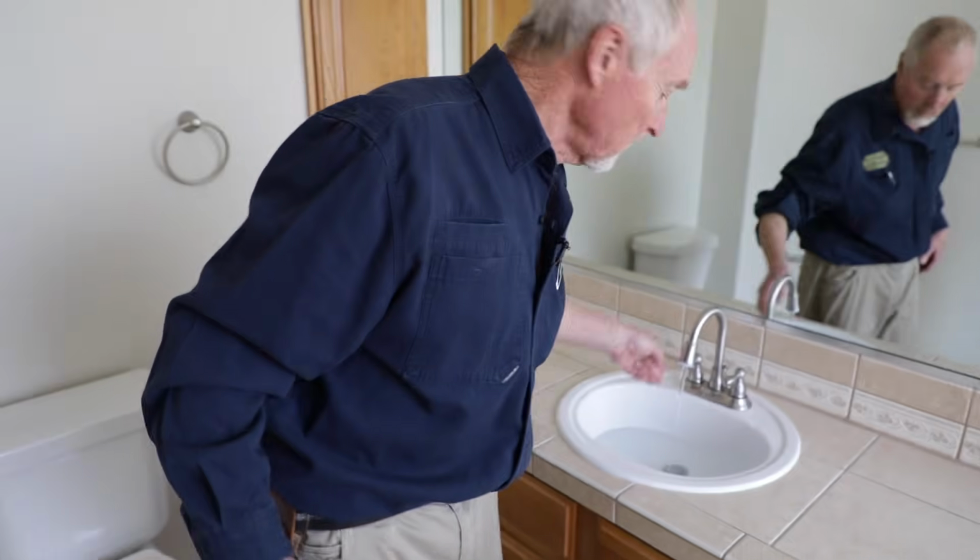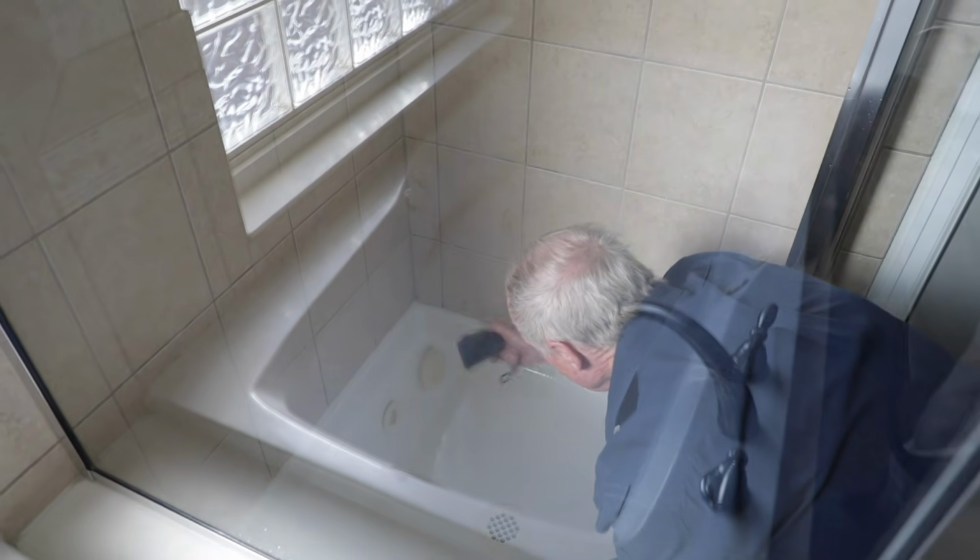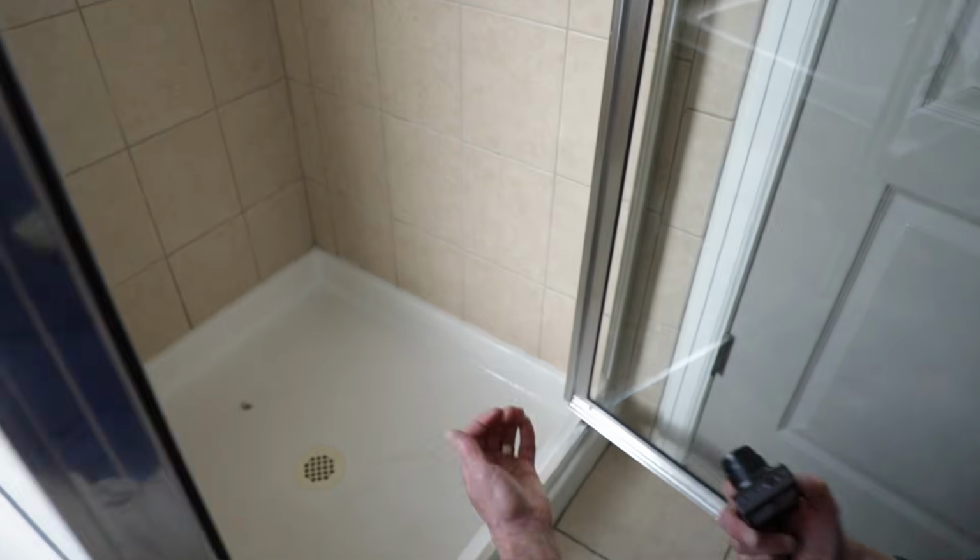So I'm going to refill my sink, get my sinks going again here so I can fill them up. Check my shower while the sinks are filling. Something we see here is we had some moldy caulk, and instead of scraping that out, they came in and caulked over the top of it, and that moldy caulk bleeds through the new caulk.